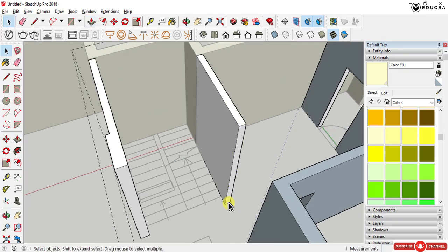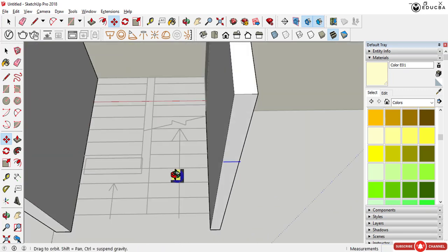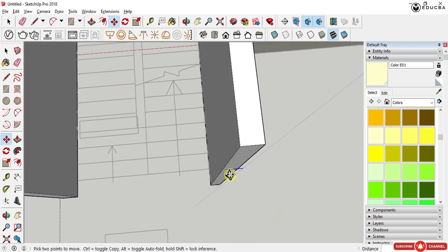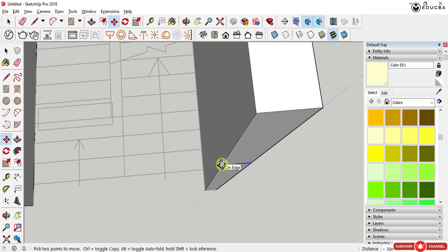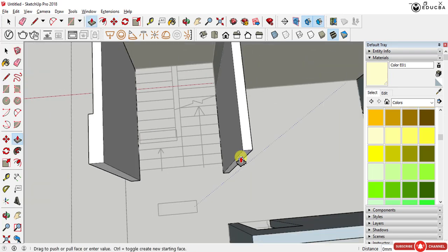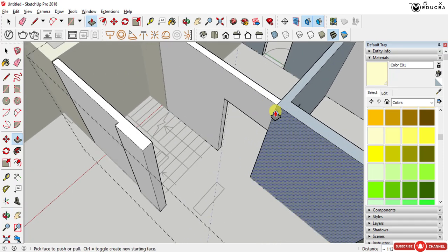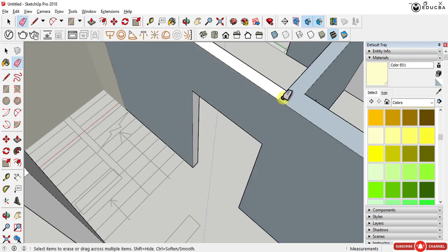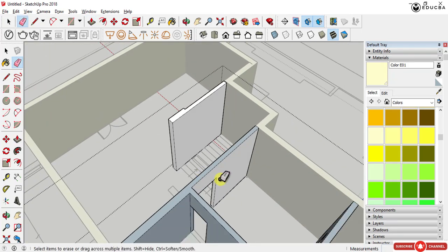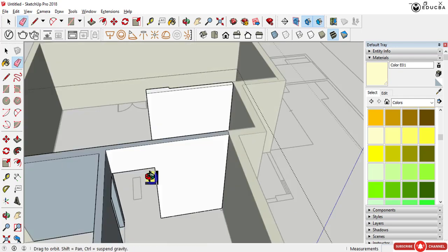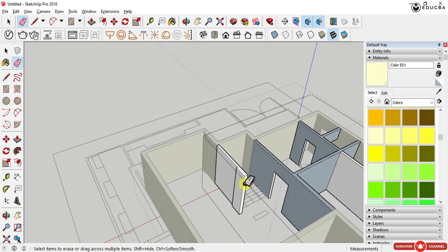Here we are going to use the same technique. We are going to move with Control, 2200 mm to the right. When we enter, we get a point. You see this point is outside the line, I can move it on the green axis. You can see the third plane is formed. By pulling, I get a door again, which will act as the archway. You can see the line has now come to the same color as the plane, which means they are now a single plane.